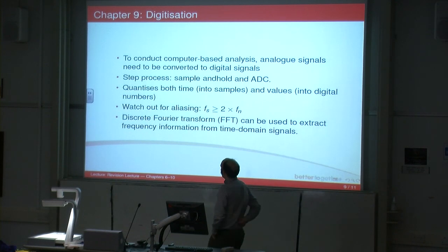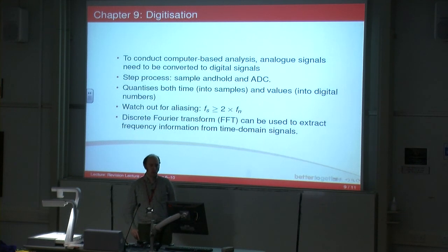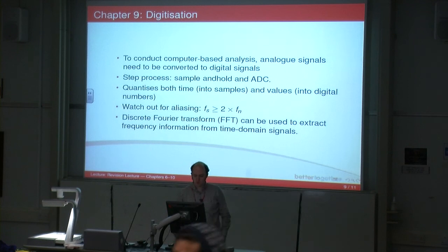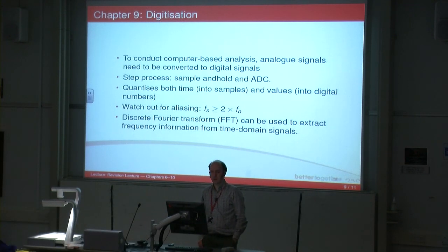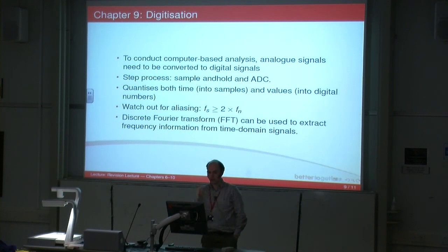Essentially, digitisation: if you're conducting computer-based analysis on a system, you need to convert the analog signals into digital signals for the computer to be able to work with them. There's a two-step process. The first step is to sample and hold, which essentially quantizes the time domain into certain sample numbers, and then you convert the analog signal to a digital signal.